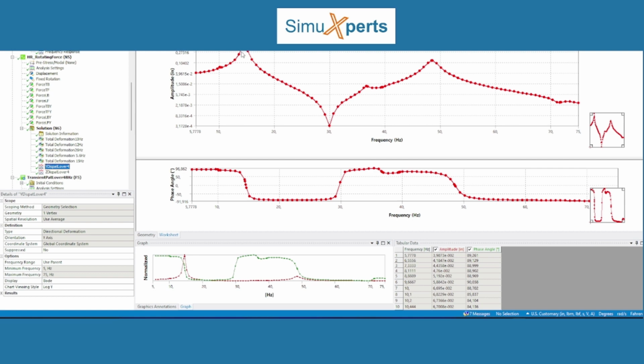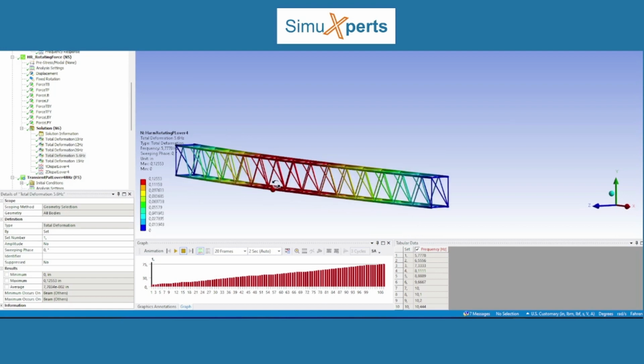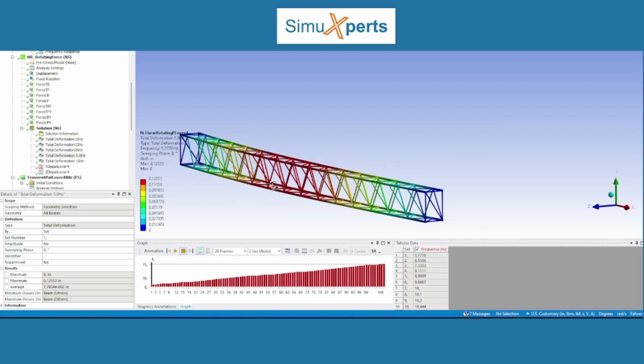So we've isolated a sufficient amount of frequencies to represent clearly what the response is. Now let's look at 3 deformation patterns. The first deformation pattern is at 5.6 Hertz. It's actually the first set of results that we solved for. So this is the displacement that we get, the total deformation.